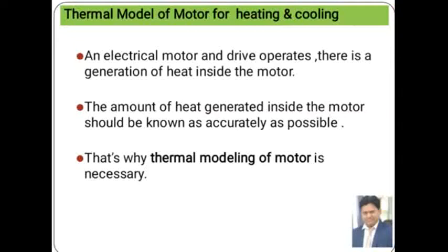During operation, heat is generated in the form of losses like copper losses, iron losses, and many more. And heat is dissipated, also due to the cooling fan and enclosures. That's why thermal modeling of the motor is necessary.